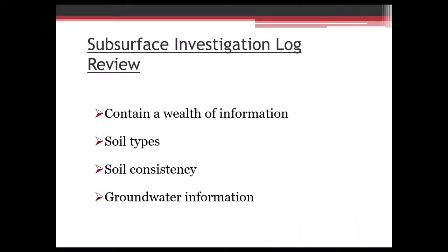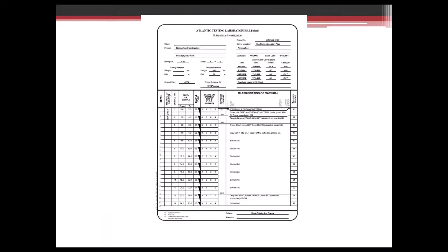So now we'll talk a little bit about subsurface investigation, or more commonly boring logs. They contain a real wealth of information, all kinds of soil types, consistency, and groundwater information. So if you look at this project here, up at the top, you have information on the project description, where the project was, what the purpose of the boring was. You have a section there with groundwater observations.